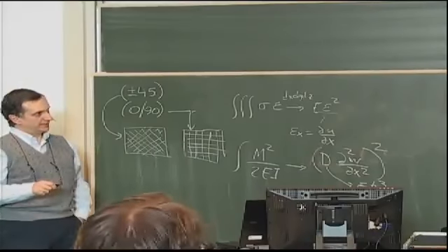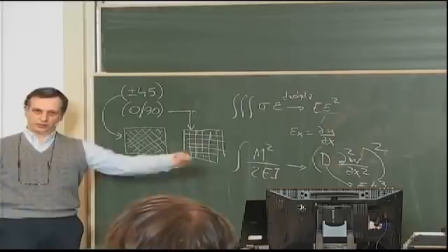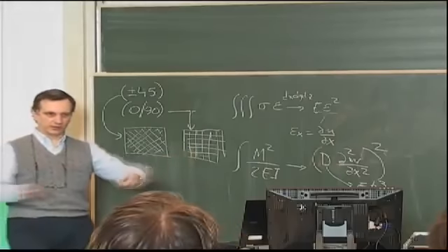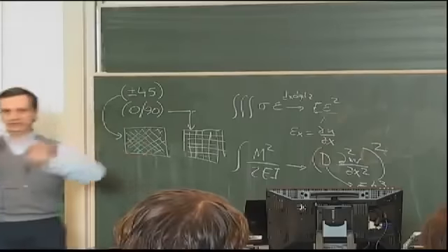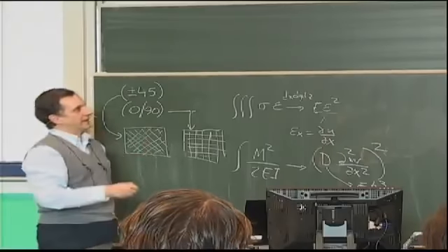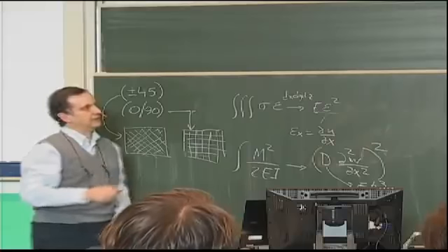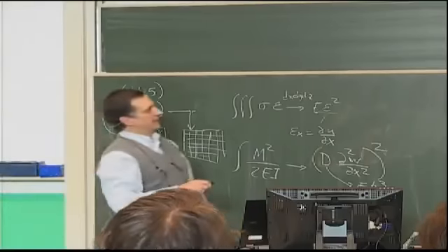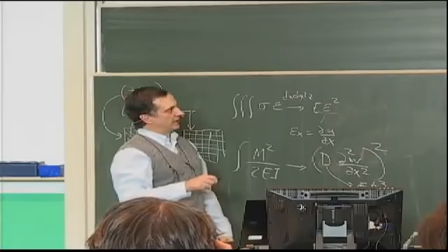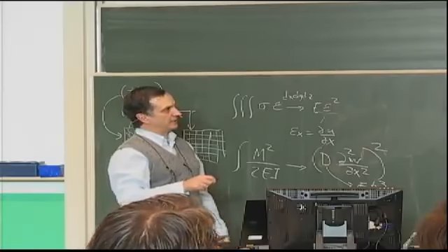Membrane energy, so energy stored in extension, in-plane shearing or contraction of the plate. Bending energy, stored in bending in any direction or twisting. And then the coupling, which is the green mess in the middle, which involves the B matrix. That's the one where you actually combine in-plane displacements, U and V, with out-of-plane displacement W.